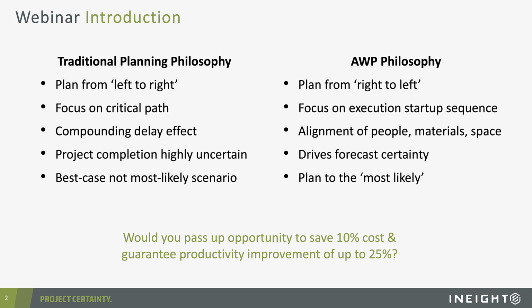Now, this concept of what we call the path of construction, it's really all about the sequence of steps for execution. That's very different to focusing, as we have historically, on the critical path. There may be mission critical steps during the startup sequence that are not necessarily on the critical path, but are absolutely needed in order to execute that startup sequence. And really, that is the thinking behind defining what we call the path of construction.